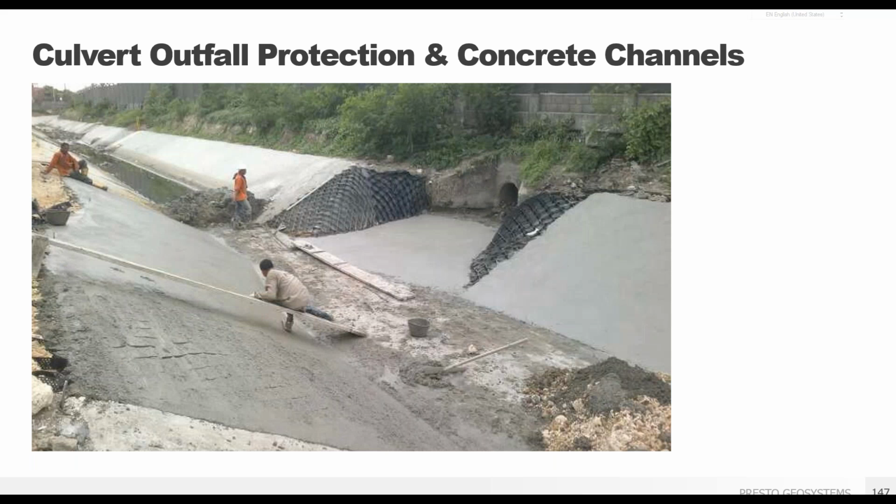Outfall areas can be challenging because they typically have high velocities and shear stresses, more so than the channel as a whole. The water in these areas is turbulent rather than laminar and smooth, which can cause its own set of problems. Using the GeoWeb system can help mitigate these concerns, especially when concrete is used as the infill, since turbulent flow and high velocities are not an issue.